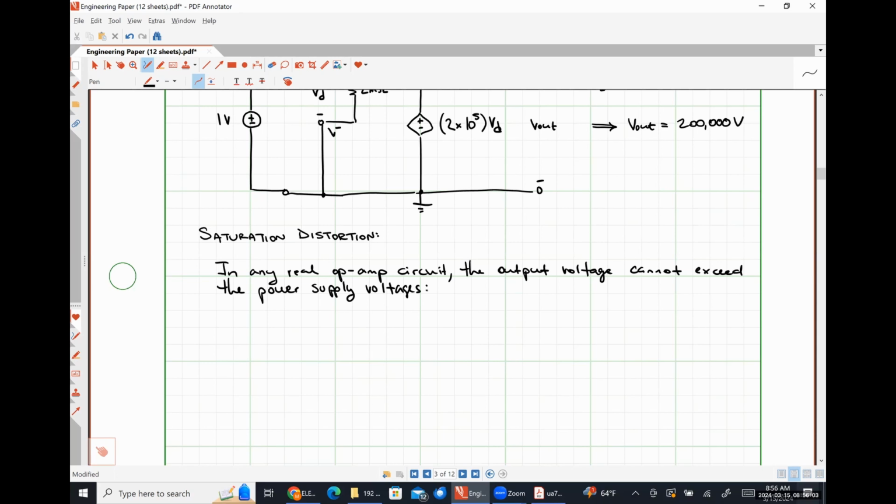So in the context of electrical engineering, what saturation typically means is that a change in the input signal does not cause a subsequent change in the output signal. So we can keep driving the input signal up, but the output will never exceed that 10 volts. So we say that the output is saturated to the supply voltage. Okay? So mathematically, this can be represented like so.